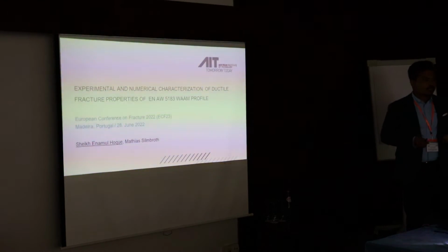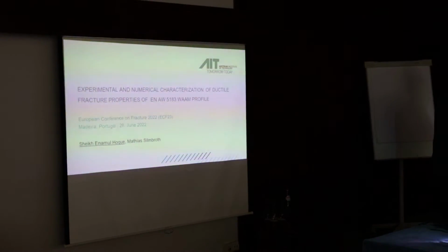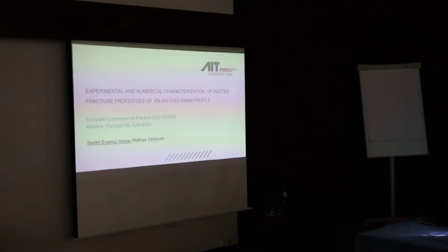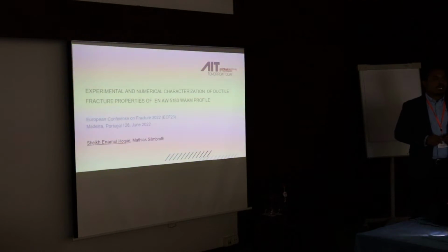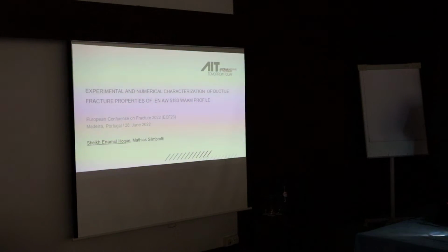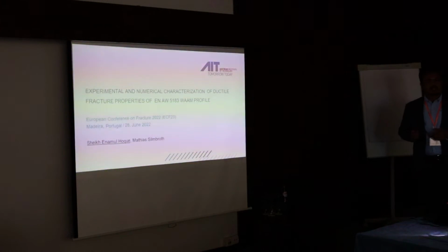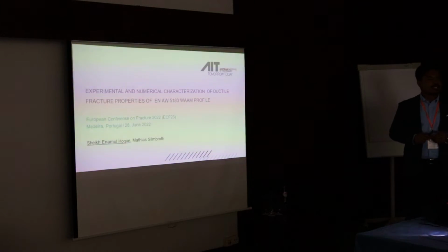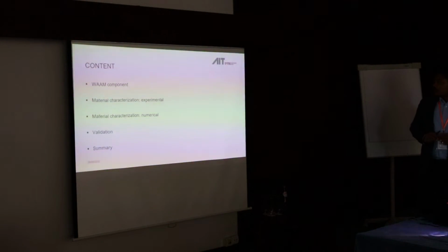In order to do the crash simulation, I need a material card. In this context, we actually need a plasticity model and a ductile fracture model. In the next couple of slides, I will briefly show you how I calibrated them. It's not really fundamental research, it's pretty much standard engineering practice, but from the material point of view, probably it's a little bit new. I will not read the content.